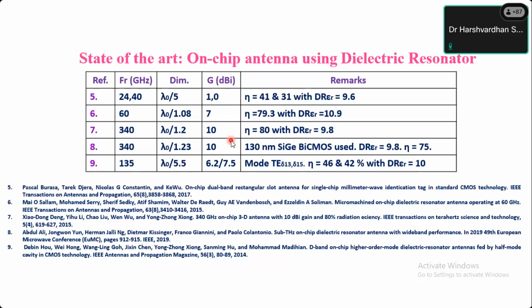And because of that, I told you why this is mostly a receiver antenna. Because of this low gain, the on-chip antenna has a very small working area. It can only be used for the micrometer or millimeter range, or maximum 1 meter. That is the range where we can use an on-chip antenna. So it can receive well, but when it comes to transmitting, it will radiate for a very short distance.